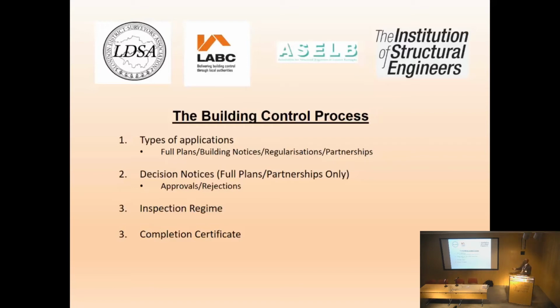We've got building notices. That was largely brought about for your smaller bits of work, toilet under the stairs, things like that. We don't check those applications. There's no statutory requirement for us to check it. However, one of the things in Hillingdon that we do, if we receive a building notice and there are any structural aspects to it, we check the calculations on that. Regularisations are for applications for works that have started, and an application has not been submitted.